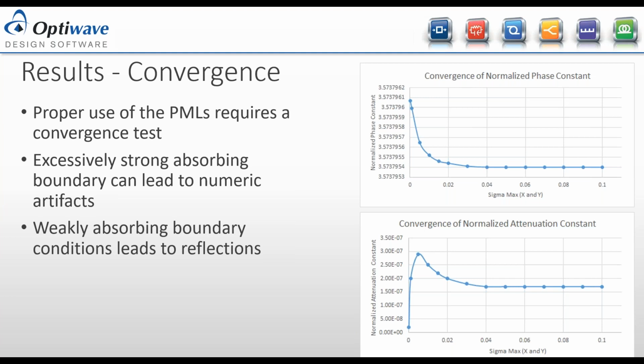That means you give it a refractive index, a permittivity, which could be complex, anisotropic, or absorbing, and then we will tell you the results of that material and how that affects a wave traveling through it, or the modes that will travel through that type of material. However, we won't tell you how to calculate the band gap of such a semiconductor. This is an optical simulator. It's not going to simulate electrical band gaps in the semiconductor.